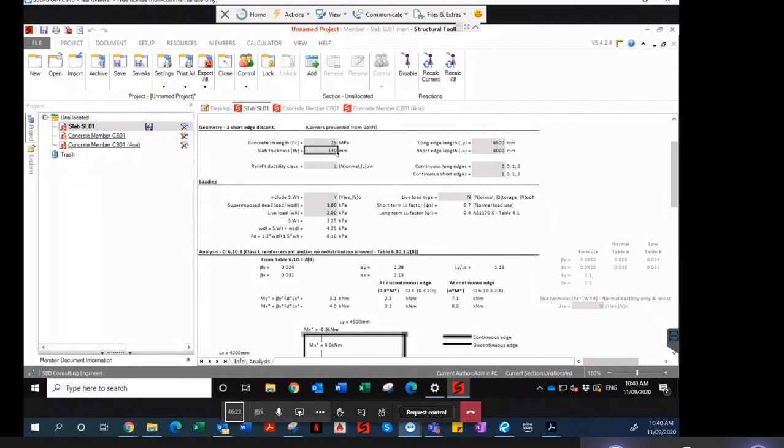So that's the reason why we wouldn't go anything less than 130. The minimum we keep at 130, and in some cases we can go higher. We can start to change our slabs and make it 140, but it depends on a case by case basis. Does it make sense?